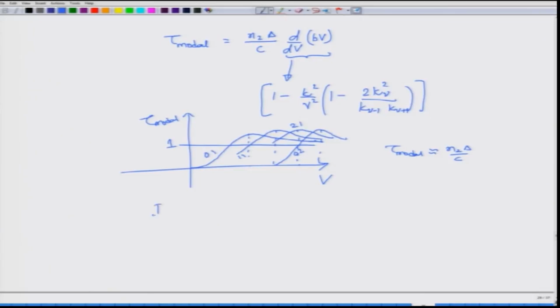And this intermodal delay that I talked about essentially asks you to find out the maximum excited mode, for which you have a max value of V, and then you have a min value of V. So, what is the delay in arrival between the max and the min values? You can use another equation for that, which will give you approximately this condition. Of course, this condition is not okay for nu equal to 0 and nu equal to 1, but for other modes this is reasonably okay.